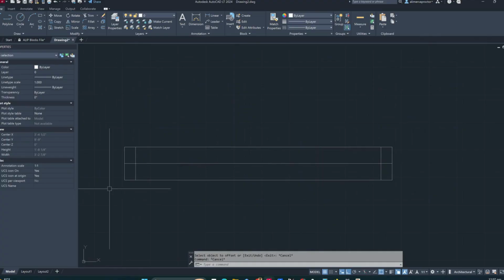So this window is gonna show us, technically, in your hung windows, you have the top part that you can push up, the bottom part that you can push down, right? So that's what we will be drawing, right? So if you go to dimensions.com and put in hung windows, you will actually see what we're going to be drawing. You will actually see that in plan, right? So we're going to do that, and then from the center line, we're going to offset 0.5, go up, right? 0.5 go up, simple as that.